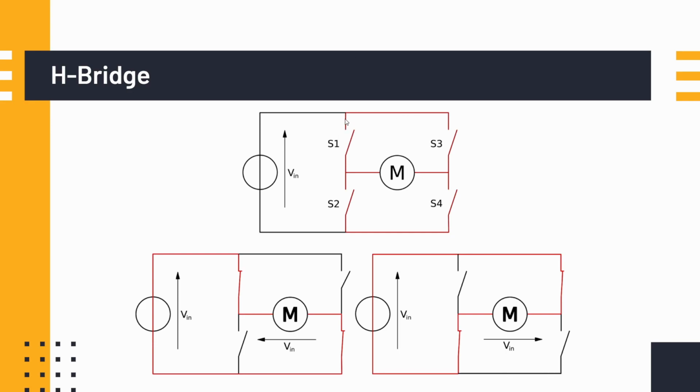An H-bridge has 4 switches, and these switches control how the current is going to go through your motor. If all the switches are open, there's going to be no current flowing through your motor. It's going to be off, right? If you want your motor to spin in, I think this will make it spin clockwise. If I'm not mistaken.